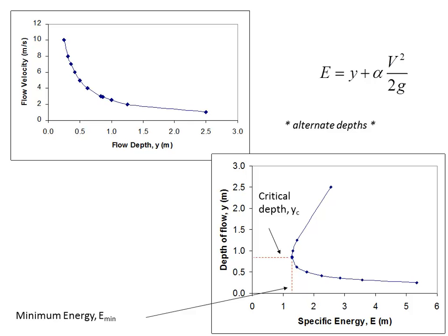The critical depth. Remember that you've classified already supercritical flow and subcritical flow. Well, you didn't know it then when you calculated it the first time, the Froude numbers, but subcritical flow is any time the depth of the water is deeper than this critical depth. And so this is the subcritical region because the water is moving slow, subcritical. Below this line, if the depth is lower than the critical depth, this is the supercritical region, supercritical flow.